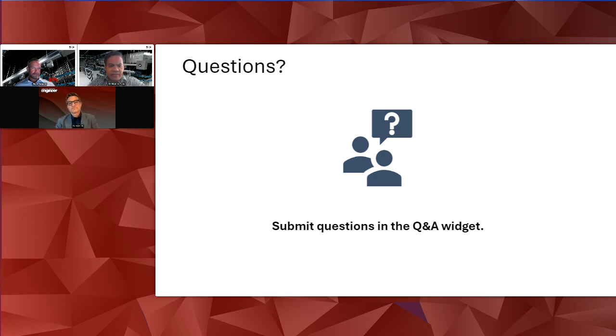There's a few questions in the Q&A regarding short circuit and rack power and it being a little bit lower. We still generally see low rack short circuit, especially in lease spaces and colo environments. The way that's addressed is either fuses or current limiting breakers.